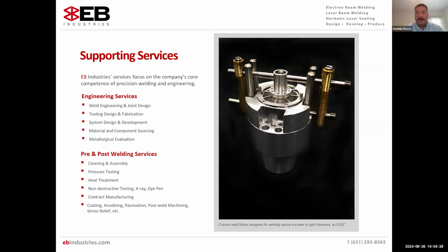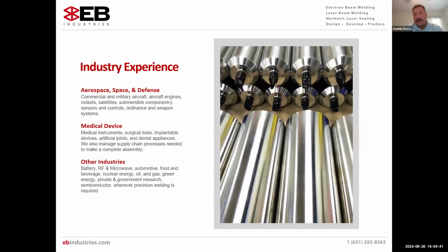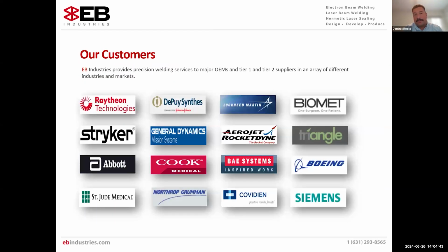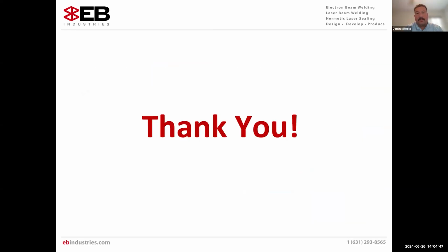We have to make sure the part is fixtured and secured properly so that while our CNC program is moving, the part is not. So in a prototype quantity where the part is difficult to fixture, it may lean towards the argument of being worthwhile to TIG weld it.